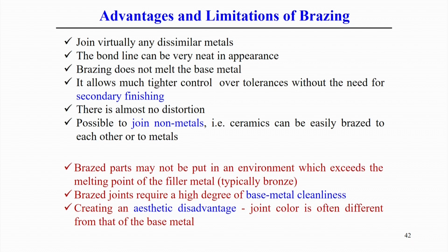But there are also some limitations of this process. Definitely, the brazed joint cannot be used in an environment where the temperature exceeds the melting point of the filler material, otherwise it will lose the strength of the joint. So, the limitation of this process is that the joint can be used only below the melting point temperature of the filler material.